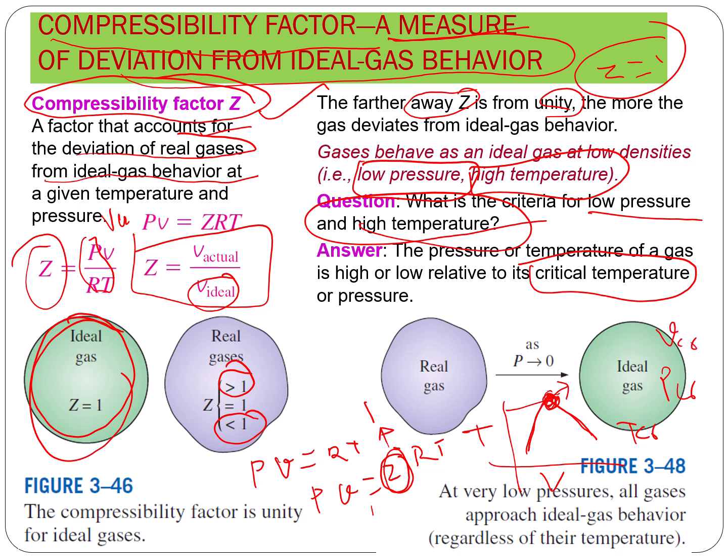These are the standard values. For a given substance you have a specific value of critical temperature and critical pressure. We can get these values from table A1. I'll show you where we can find it, but remember, the key point from here is you cannot use the ideal gas equation for any gases.